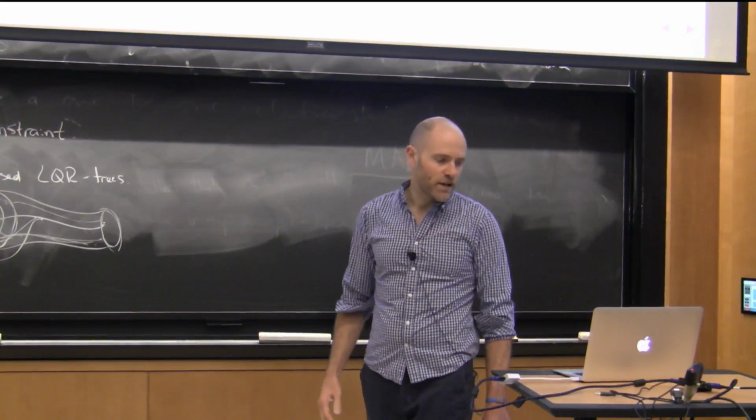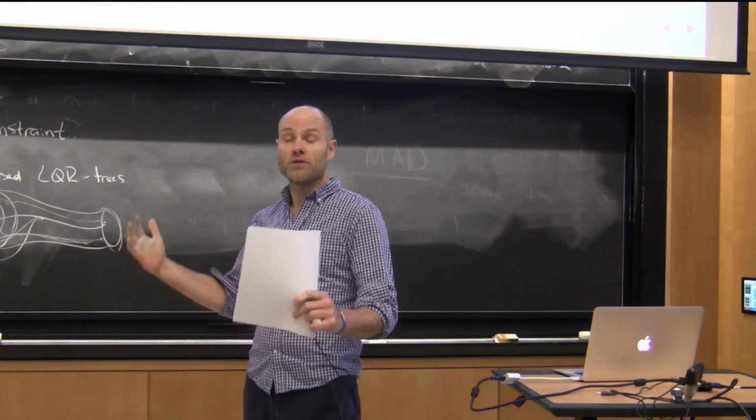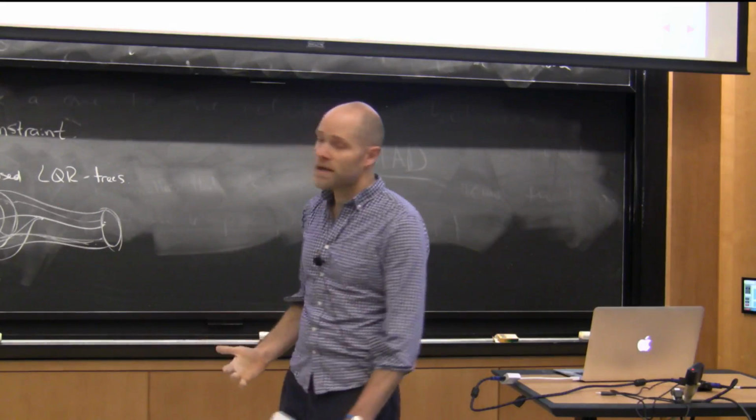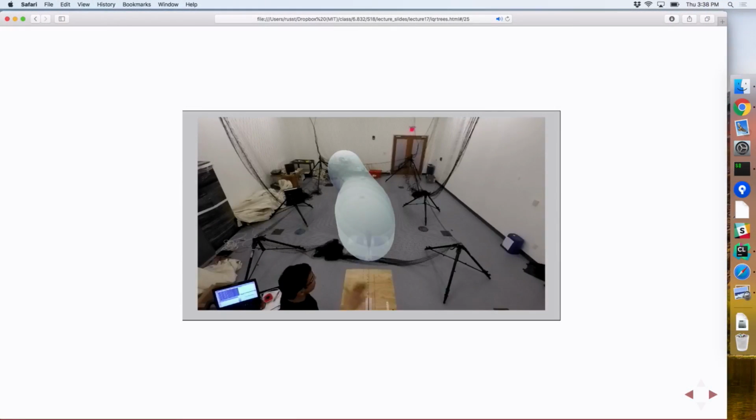And then for the online planning, this was Ani Majumdar's thesis. He showed this set of tools where you pre-compute a library of funnels, let's say I'm going to go straight, I'm going to bank to the left, I'm going to bank to the right. He developed the tools to be able to trim the funnels at runtime to account for new constraints. And how do you come up with a sufficiently rich set of those trajectories to fill the space? And he was able to execute high performance maneuvers on a small aircraft in a ridiculously small flight arena, which is our holodeck, right?